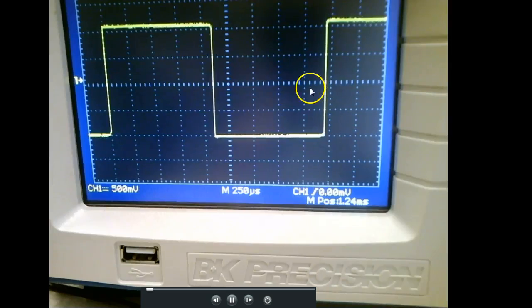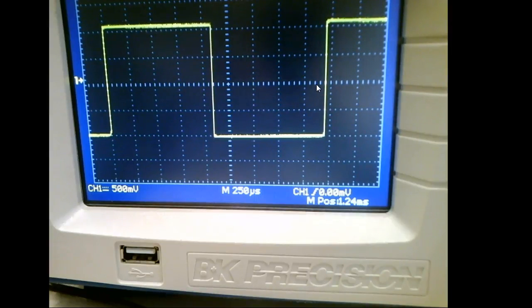Yeah, guys, what I was telling you: if I wanted to measure the frequency, I'd use a digital device called a frequency counter. An oscilloscope is fairly accurate, but not perfectly accurate because of these minor divisions. If it's out past a mark, we usually just round it. If it's closer to the one on the right, we'll count another 0.2. If it's closer to the one on the left, we'll leave off at 0.2. It's accurate enough so you can figure out what's going on, right?